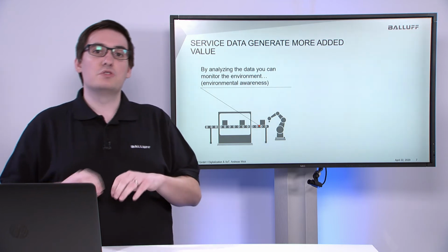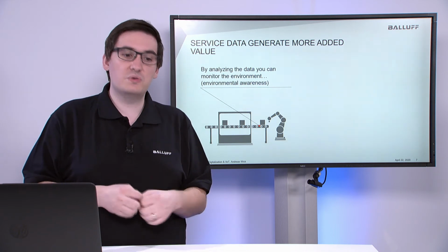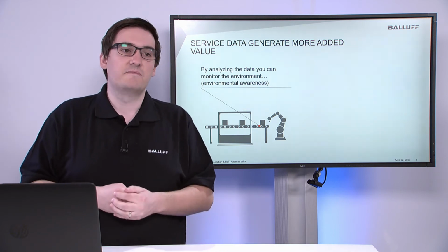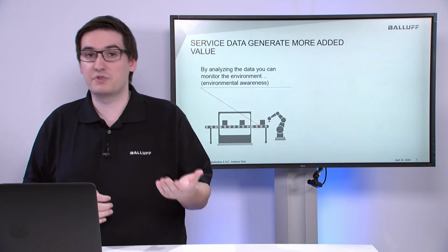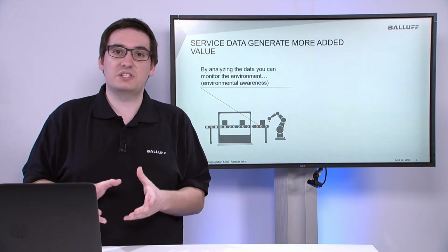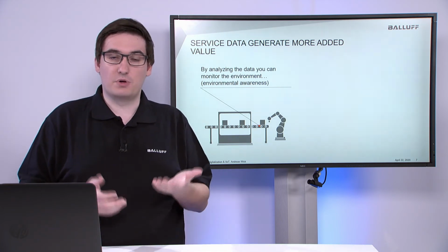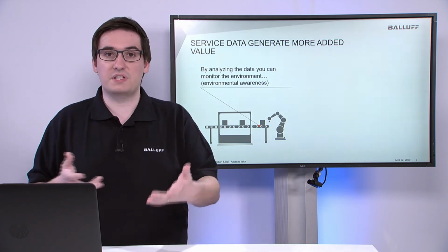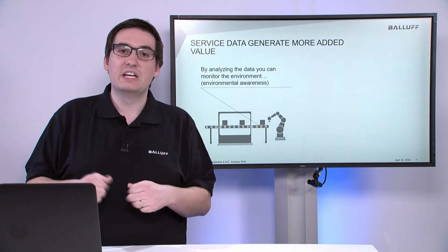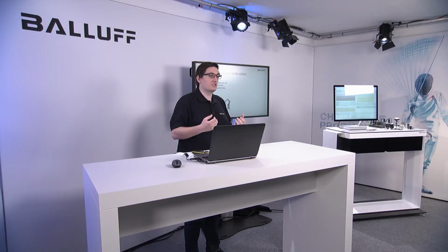One thing would be to monitor the surroundings of your machine by using these additional data. So for example, if you're thinking about the internal temperature value of a sensor, and you have different sensors in your machine, and one of these values is rising, then most likely a problem with the sensor occurs. But if all of your sensors are detecting the same temperature rise, you may not need a dedicated temperature sensor to measure that you have a deviation in your internal machine temperature range.